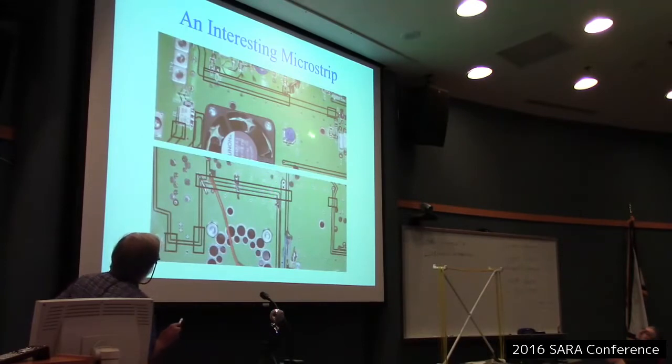By the way, the particular receiver started out at 2.5 dB noise figure, and after just fixing a lot of grounding related problems, it went down to 0.8 dB. So that's a substantial improvement in noise figure, just making sure the ground signals go where they're supposed to.